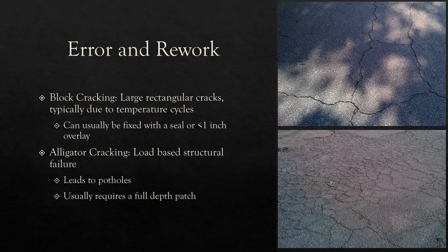Alligator cracking, on the other hand, as seen on the bottom right there, is usually indicative of a structural failure of the asphalt. Usually you're going to have to dig up the whole thing and start over before you end up with a lot of potholes and a lot of angry drivers.